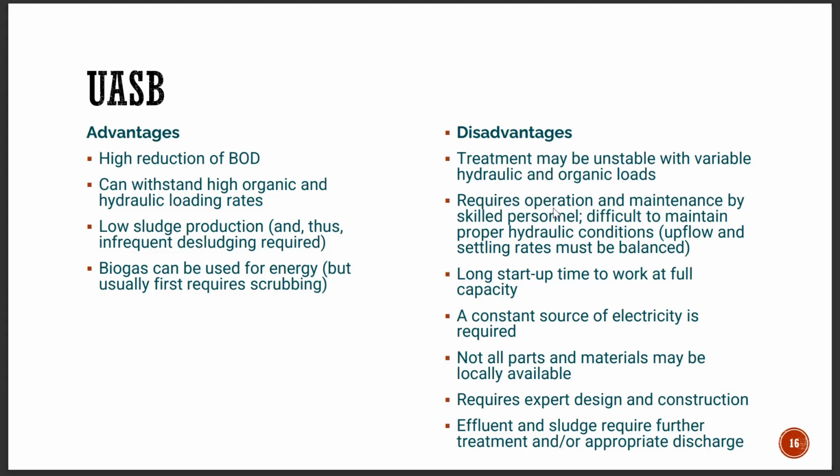The disadvantage of this is basically the treatment may be unstable with variable hydraulic and organic loads. Okay, so it would be better to make sure that there are no huge fluctuations. Then this, as we said earlier, requires operation and maintenance by skilled personnel, and it is actually difficult to maintain proper hydraulic conditions. We have to ensure that the upflow that is coming and the settling rates need to be balanced.